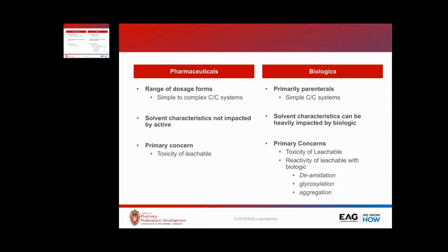However, there are a lot of significant differences. The first is that the solvent characteristics can be heavily impacted by the biologic. What this is referring to is if you have an aqueous system, but you have a biologic, a protein or an antibody or something like that in there, you can actually have leachables migrate into the final product that you typically would not expect to be soluble in an aqueous environment.